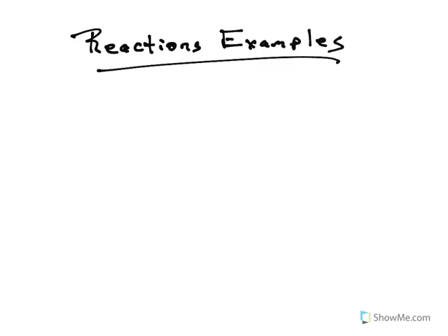It's supported in some way. And we saw that there are three basic types of supports. The first is called a pin support. And when you have a pin, you can have a vertical and a horizontal reaction. Call it Ry and Rx.